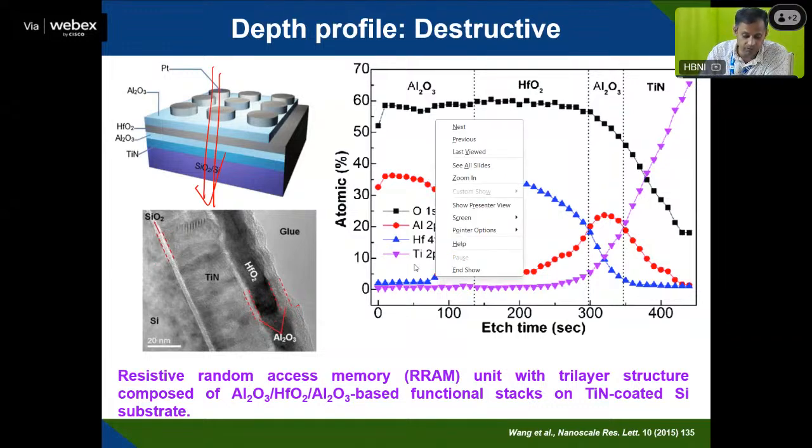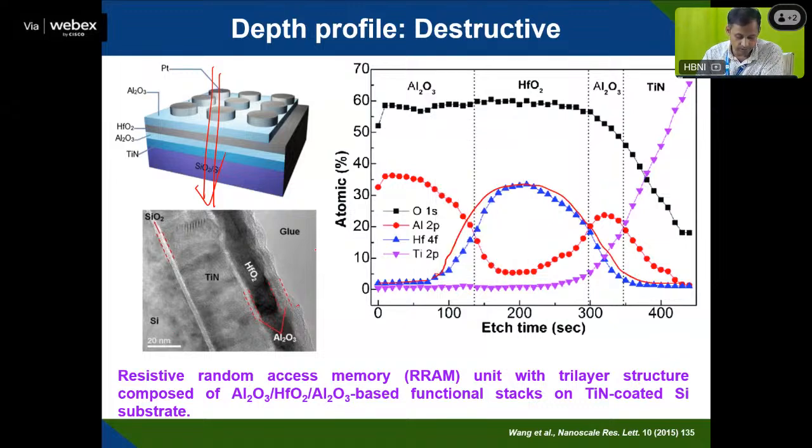Initially, on the top surface, you have platinum, so in the platinum zone there is no peak. Then the aluminum region slightly increases, reaches the maximum, and then decreases. For Al2O3, you can see how it varies inside; initially it's high at the top surface, then it decreases.